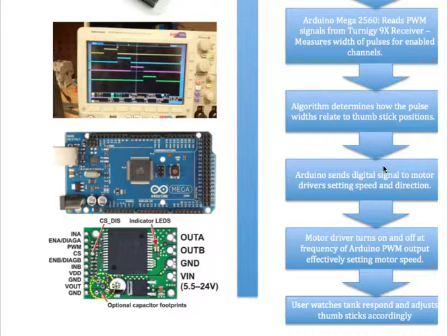Basically, the average value sets that motor speed because we're switching it so fast that the RMS voltage, the average voltage to the motor, is that effective 12 volts, which means we will be moving the motor at 50% of its rated speed.